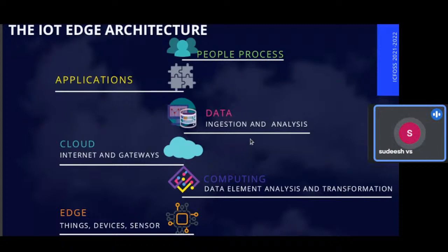So first we need to sense and process the data. We sense the data in the edge section, which is not low power devices, and send it to a central device, the gateway. When the gateway receives the data, it analyzes the data. Then the meaningful data from the gateway is stored in the cloud or moved to big data analysis. That is the basic IoT architecture we commonly use.